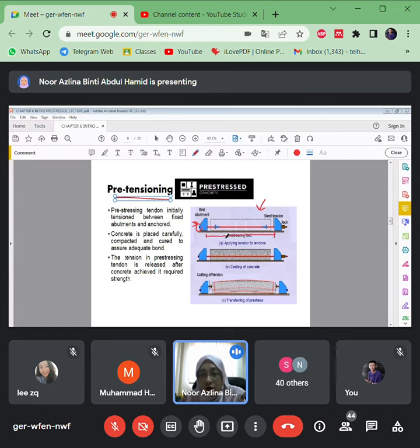There will be formwork and so on. At the other end, we provide the hydraulic jacks in order to pull out the steel reinforcements, and then also to release the steel, and after that we have to anchor back all the tendons here.